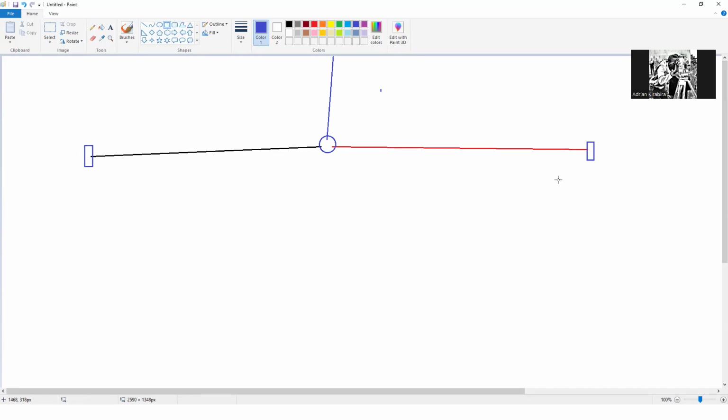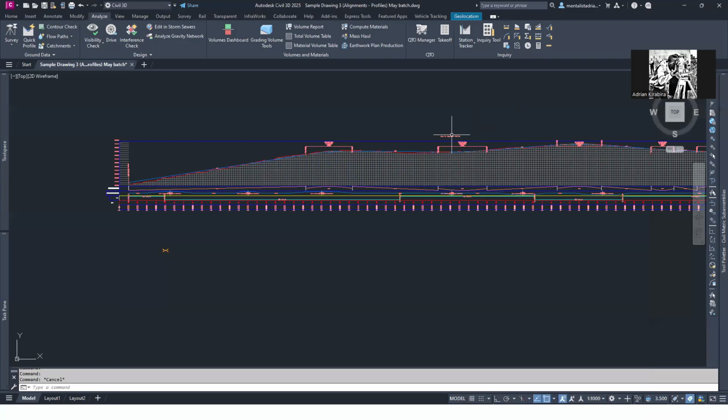Apart from the other things we've been doing, where you just come and put in the features you have here, it's better to first make a catalog of the things you're going to use for your network. For example, I'm going to use this number of these pipes, maybe 900 diameter pipes, this thickness, this material. I'll need 600, I'll need 300, I'll need 450. You get it. So you make a catalog of those pipes. Then the structures also, you make a catalog for them. So we have pipes and structures, and we shall be talking about that more often.